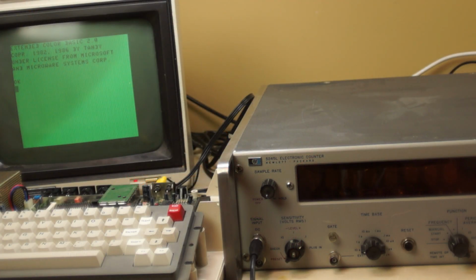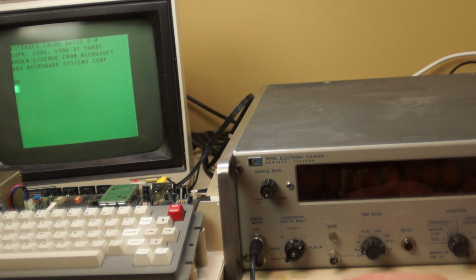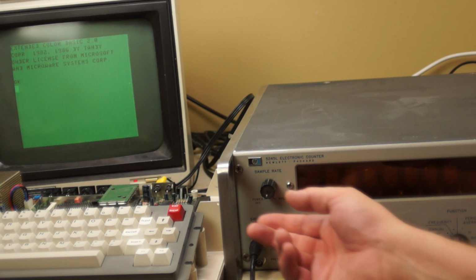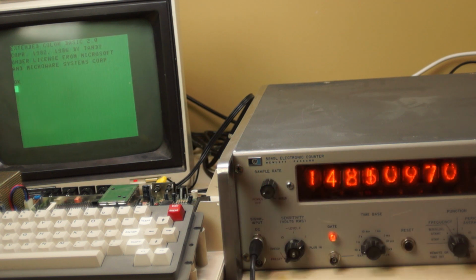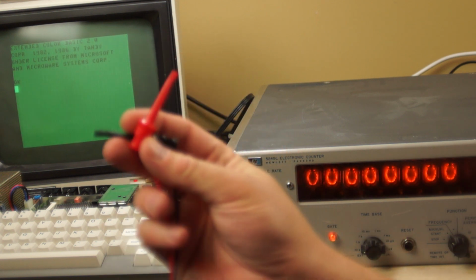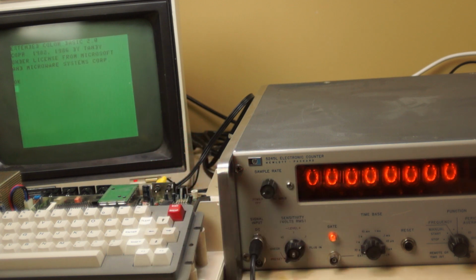Part of the fun of having a home lab is that sometimes you've got a few tools you can use in order to test a problem out. And in this case, I'm going to use my trusty HP 5245 counter, and the main reason is because it's the prettiest. So what I'll do is I'll take the leads from the counter, and I'm going to connect these up to the SCS lines, and we'll see what the Coco does when I power it up, and we'll just see how many pulses there are on SCS.